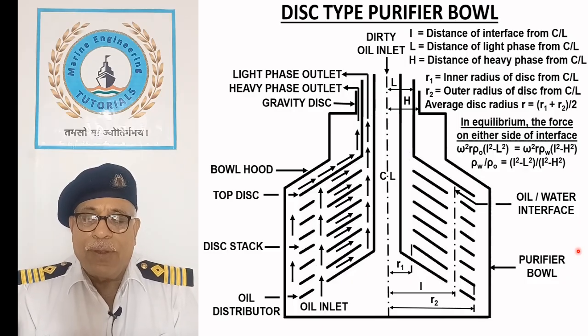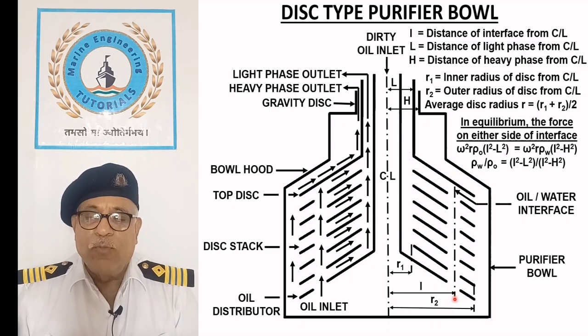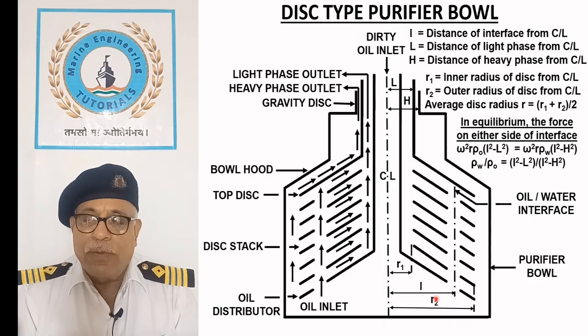For correct operation, the interface must remain within specific limits, that is, between the distribution holes of the disk stack. If the interface moves inward, water will be discharged along with the clean oil.